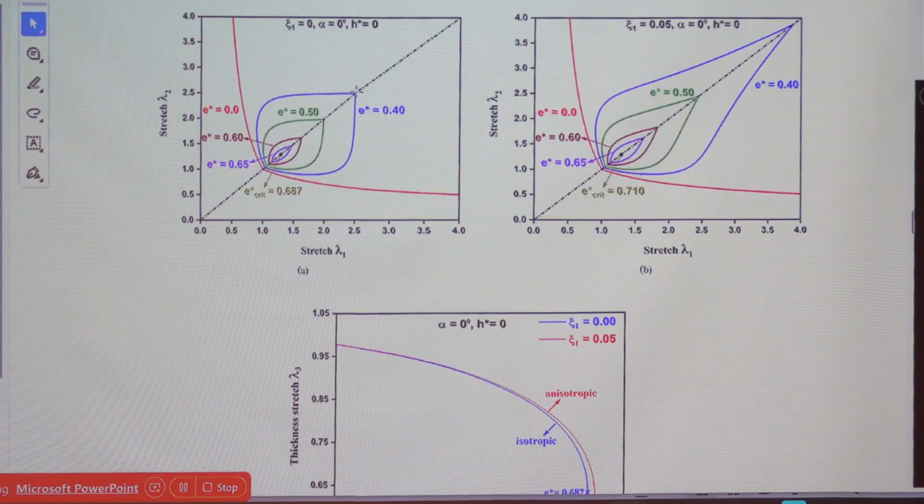So you can see what is happening. At a particular level of applied electric voltage, your tau domain will be there. As you keep on increasing this voltage, it will shrink down. And at a particular value, you can see it will reduce to a single point. That single point represents that the breakdown of the membrane will now take place. So if you keep on increasing the electric voltage, it is of no application. That indicates the occurrence of pull-in instability in the smart material. You're getting my point? So this is how the tau domain is used to find out the pull-in instability of the dielectric material.